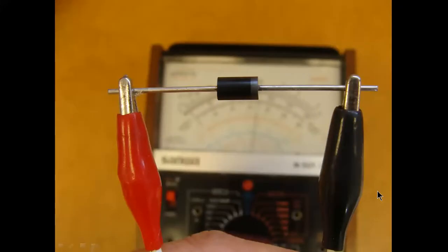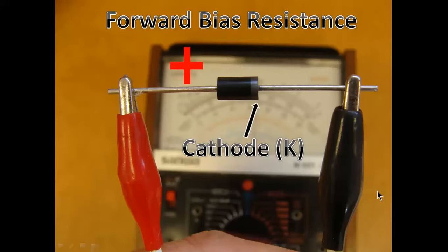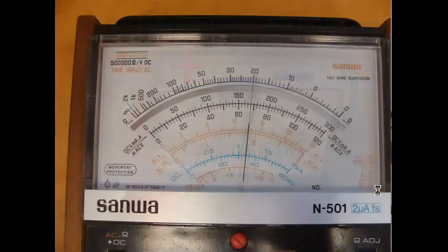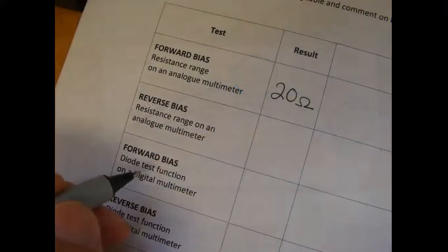The first practical task is to measure the forward bias resistance of the diode. Now we've got the cathode, which is indicated by the grey line, silver line on the diode, and we're going to make the anode positive with the red lead and the cathode negative, and measure the resistance in ohms on our meter. In this case the diode that I was measuring was 20 ohms, and we're going to record that in the workbook.